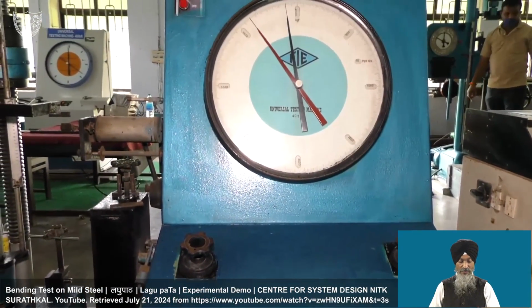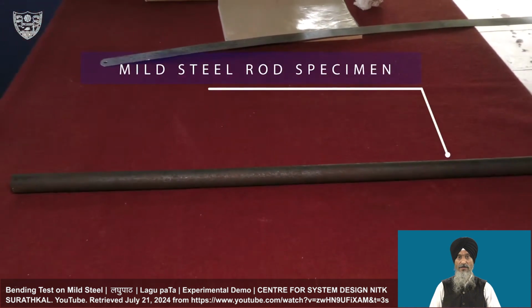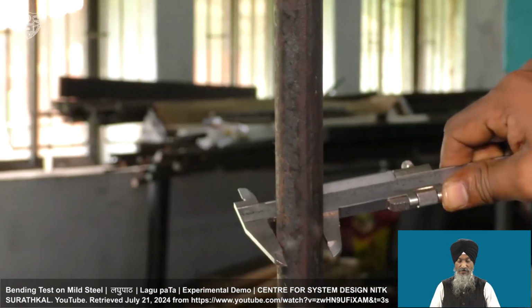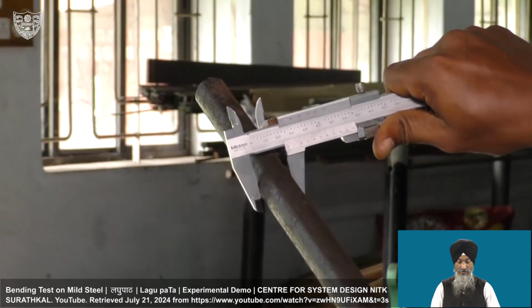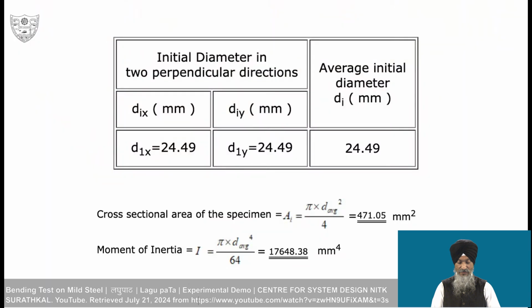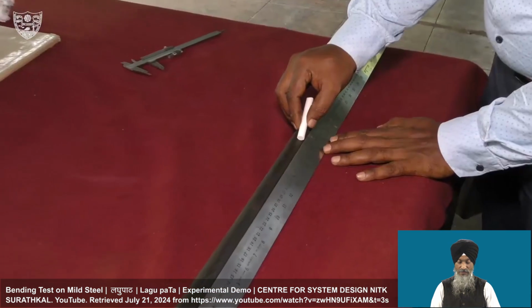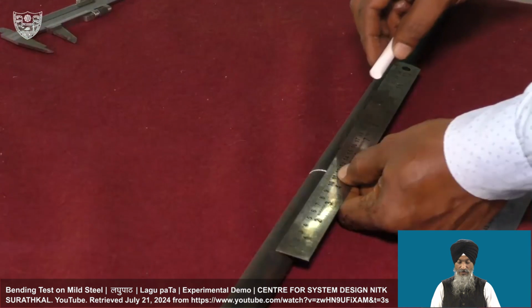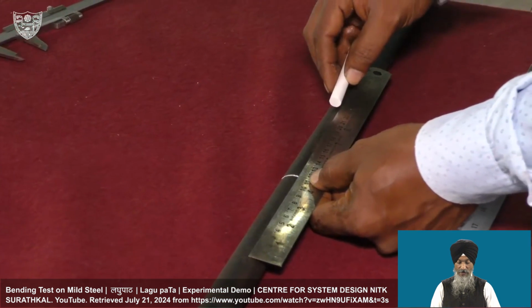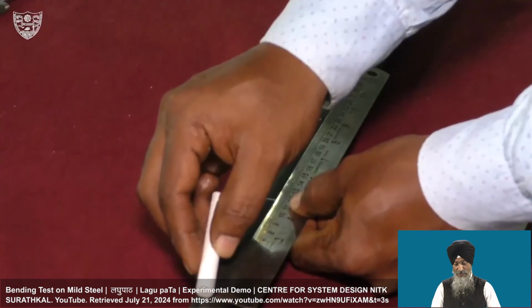You can see a mild steel rod specimen, a long specimen, where the length is 690. We first measure the initial diameter in 2 perpendicular directions and take the average. Then we measure the length and mark the specimen for the middle point and the other 2 points to keep the span at mid span and 1/3 span. So, here L is 690 mm.